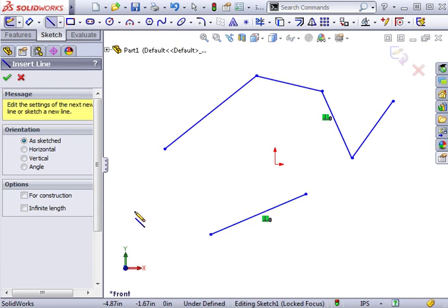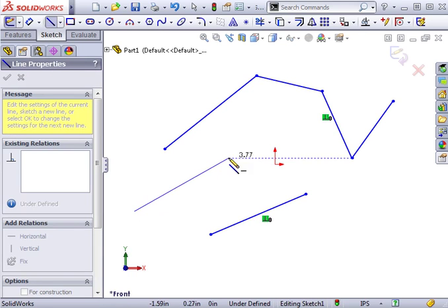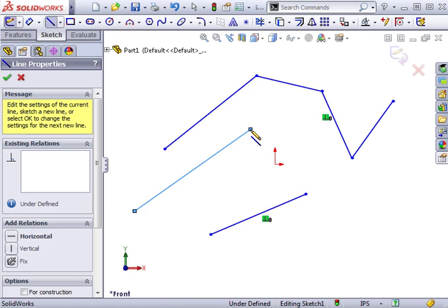Instead of clicking to begin a line segment, then moving the cursor and clicking again to add a point, you have the option of click dragging. I'll click and keep the mouse button pressed. Then I'll drag to the location where I want the line segment to end and release the button. The difference, as you can see, is that no chain of lines is created, just one segment. For those that don't want to worry about ending chains either by right-clicking or double-clicking, this might be a better method. Other sketch tools work very much like the line tool.